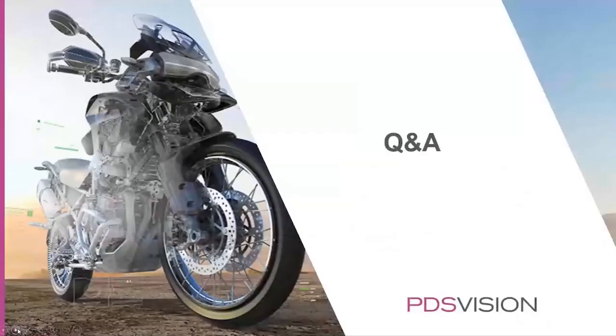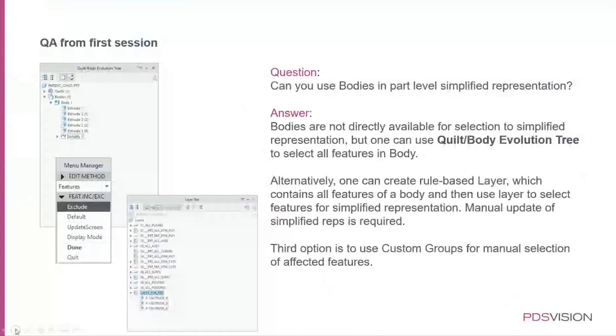Now, that was the last slide. Last time I promised to get back to you on one of the questions from the audience: can I use bodies in simplified reps? And the answer is, well, no, not directly still, unfortunately. But what you can do, with the quilt body evaluation tree, is look at one of your bodies, let's say like this. In here you have body number 1, and when you come to creating a part level simplified rep, you just exclude and pick all of them from here, and you get your simplified representation, which basically removes all of the features for that one particular body, resulting in 0 objects for it.